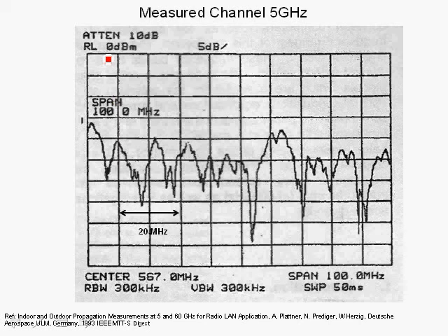The attenuation is shown here, and the units are 10 dB. So we see that within a 20 megahertz bandwidth, we exhibit what you call frequency-selective fading. In this case, we have multiple deep fades and quite a bit of fading and loss within a wide range of carriers, or a wide range of the bandwidth. Over here, you might even have very deep fades, and if you had a signal with a carrier placed in this location, you would have almost a total loss of that particular carrier.